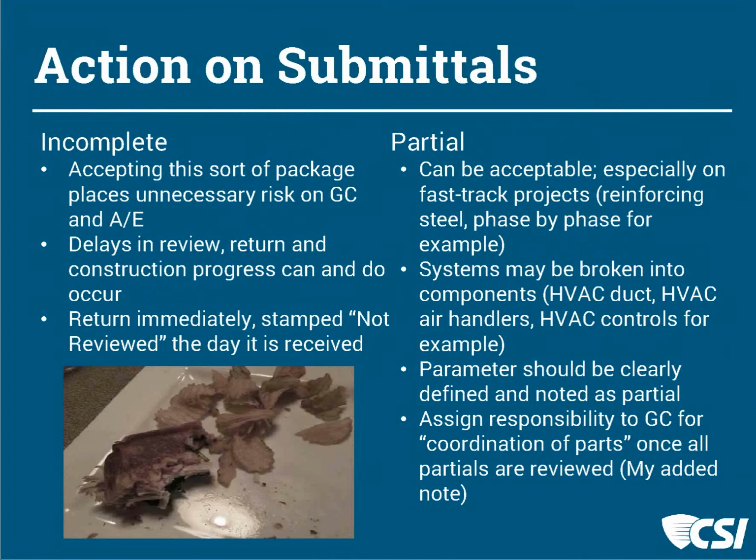It certainly causes a delay in your review, and it can impact how things turn around on the job, delivery of materials, etc. It's really important that when you receive a submittal, you open that package and look at it, even if it's a two-phase review where you look at the submittal and decide this is incomplete, stamp it as such, say not reviewed.